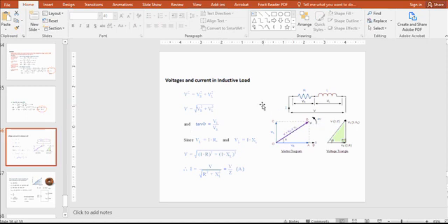Okay. Now this is a simple revision of the previous things, that is the series RL circuit. In that case we have the voltage across the resistance and the voltage across the inductance. So we know that the voltage leads in the purely inductive case. So here we have the resistive vector and the 90-degree inductive vector. By vector head to tail we get this resultant voltage, and this will be the Pythagorean theorem. Its magnitude will be calculated as this value squared plus this value squared, under the root. So this is from the Pythagorean theorem.